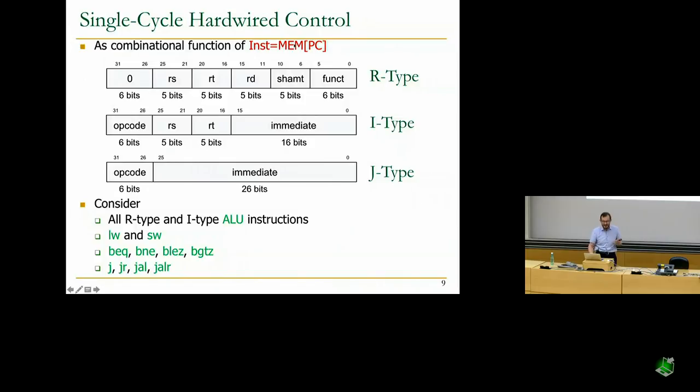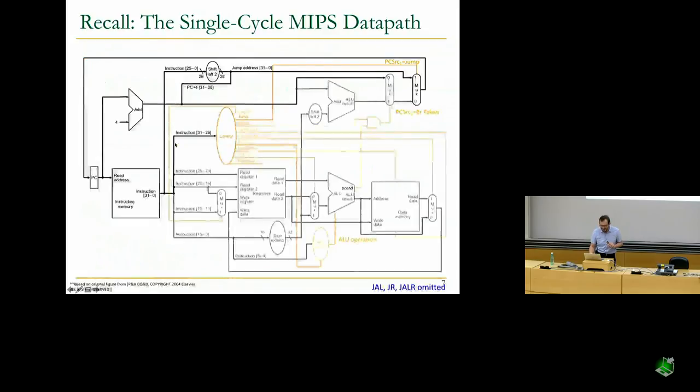Basically, the instruction is at the memory location specified by the program counter. You need to get those bits of the instruction, and the bits you get depend on the type of the instruction. And you need to decide the control signals that are controlling the data path based on the bits that you get from each of the instructions. It's clear, right? Okay, so I'll go back to the data path over here.